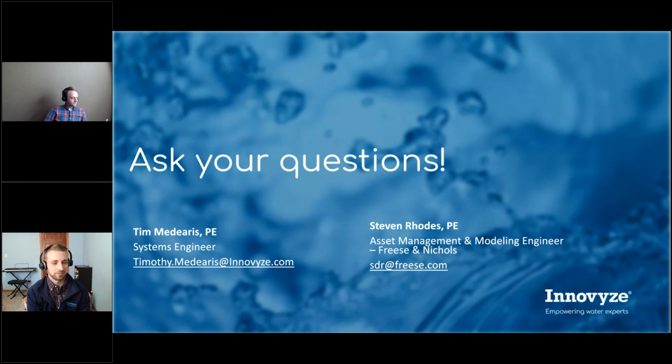Perfect. A couple of questions here for Paul. First question, did you consider an initial state run to initialize and simplify your RTC controls? I honestly haven't. We almost went down that road when we were having trouble getting one of the models to initialize years ago, but we were able to get it sorted and it worked out. But that is one option if you can't get the model to initialize. Those hot starts, as I've heard them referred to in the past, can help bypass some of that and help you get to a simulation.